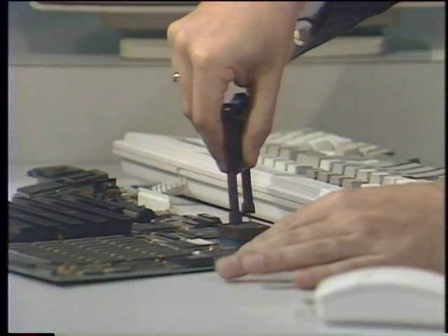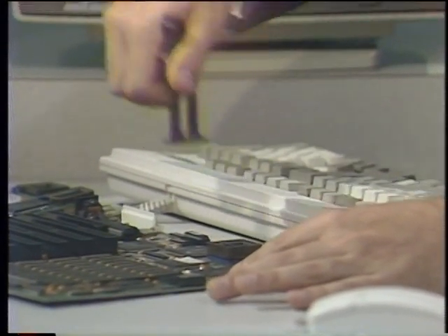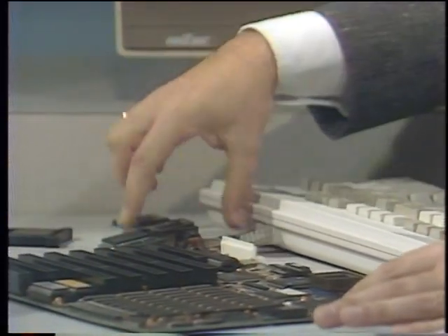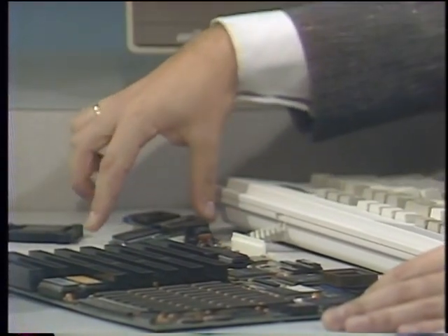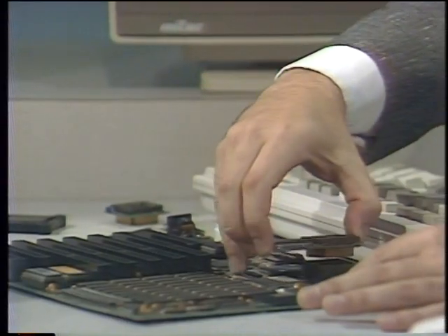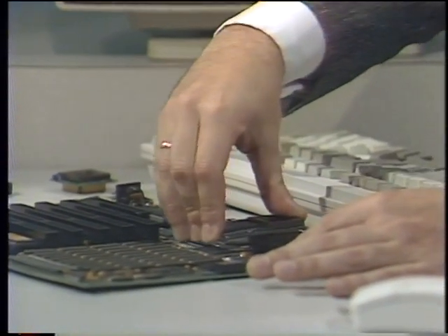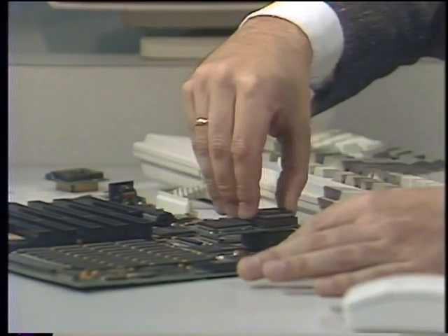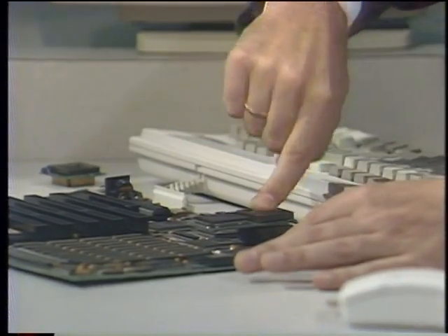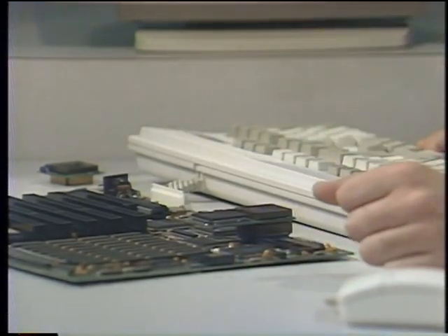Well, the charge card, we actually include all the tools that you require. Very simply, in this case, here's my 286 system board. I just place the tool, pull, and the CPU comes out. Then I get the model of charge card for my computer, plug it in, take the CPU and put it back in on top. And that's it. I've just upgraded my machine. Okay, well, it looks reasonable.